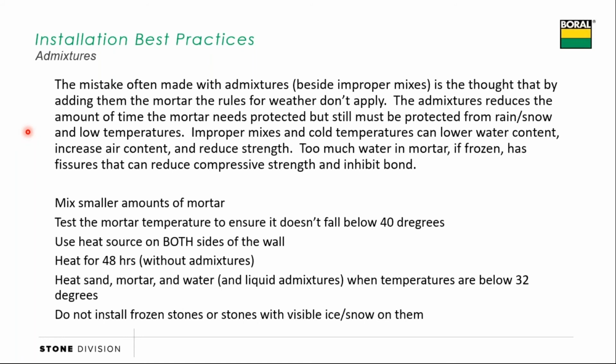I've seen some guys try to use admixtures in 29-degree weather thinking that their mortar wouldn't freeze because they put a quote-unquote antifreeze in there. That mortar is still going to freeze. So make sure you're tenting in and heating. You just may not need to tent in and heat as long.